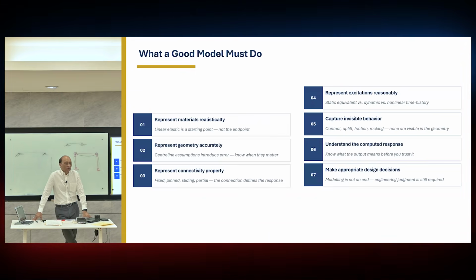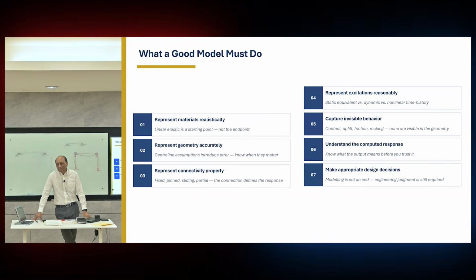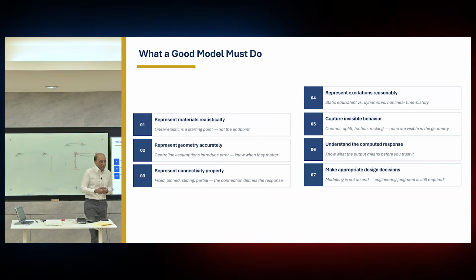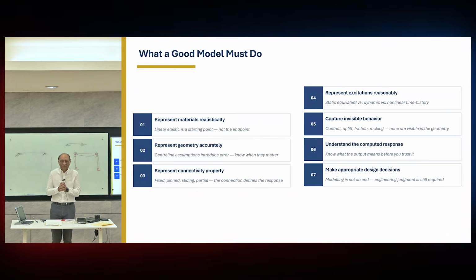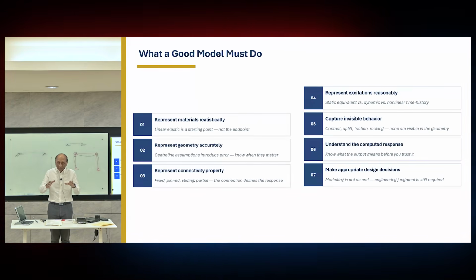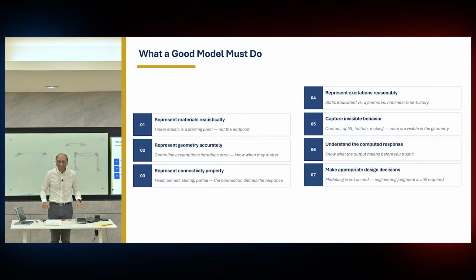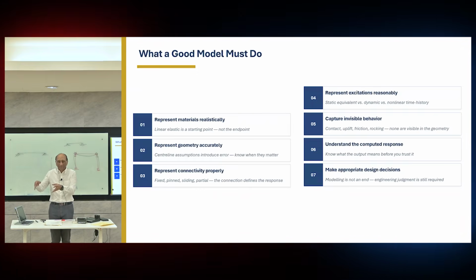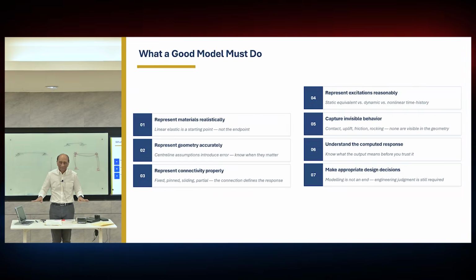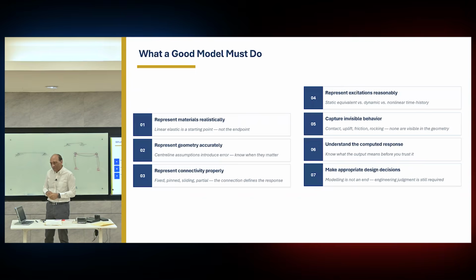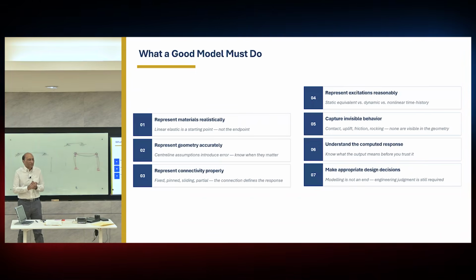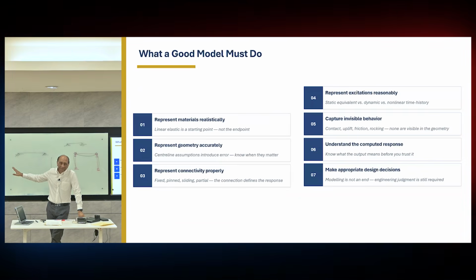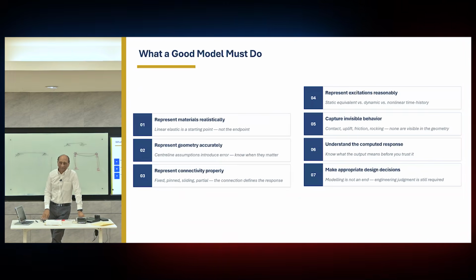The people at the site will ask you how much reinforcement you want to put here. You have to answer that. You have to make the drawing. As I mentioned to you in the beginning, I would try to do the design without calculation first. Always. Get it, understand, put all the reinforcement, design everything, no calculations yet. Then go back and do some calculations and cross-check important points. Keep the rest over there. Use my judgment. But unfortunately, now that sense isn't there. We just rely on the computations too much without thinking. That's why I want you to think from the fundamentals for the basic problem like that.